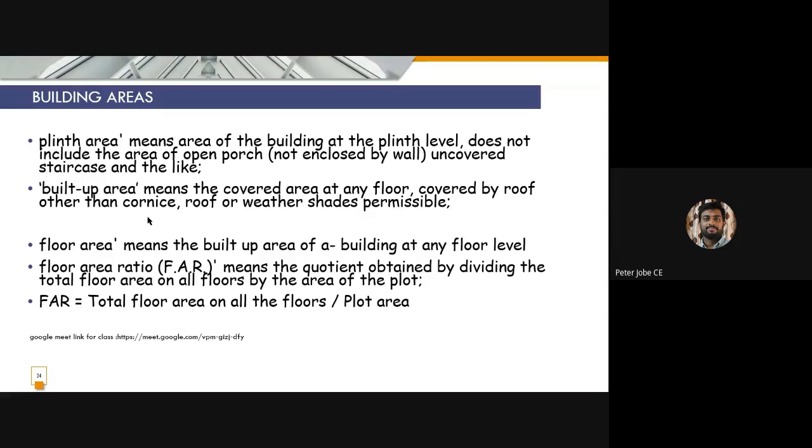So that means that open terrace won't be taken as built up area. We will take those areas only where we have built something. We won't take the open areas. And the floor area means built up area of a building at any floor level. So we'll describe by each floor area. That means floor area of first floor means the built up area of first floor. Floor area of second floor means the built up area of second floor.